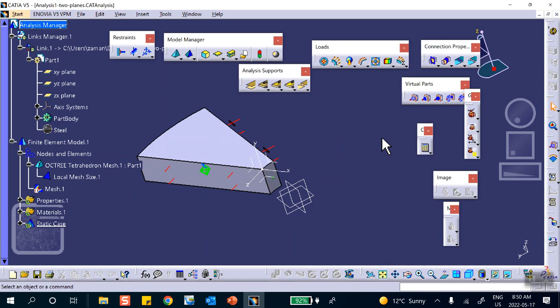Okay. Now we're going to apply the load. You go to the load. That rotational speed is causing constant speed around the circle, which will give you a normal acceleration, radial acceleration. Centrifugal force, m r omega squared. Remember? So it has to do with your speed, your angular velocity.